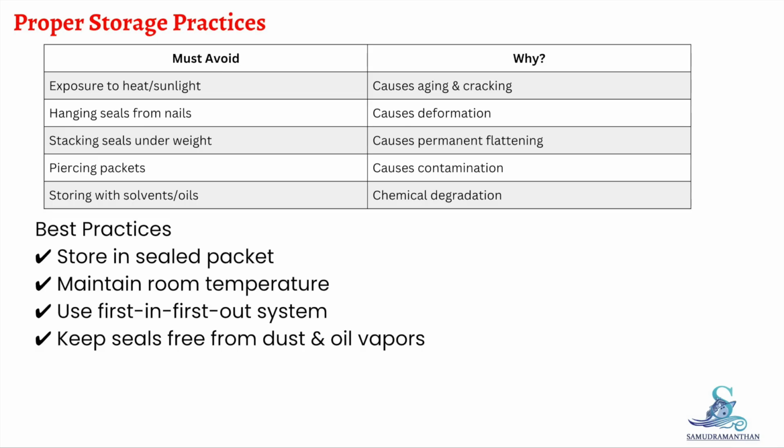Then what can be done? Store seals in sealed packaging. Maintain room temperature. Use the first in, first out method. Keep the storage area free from dust, UV light, ozone, and chemicals.